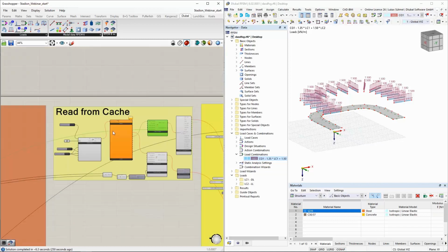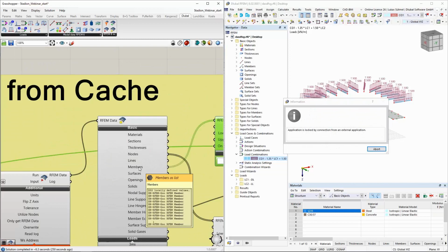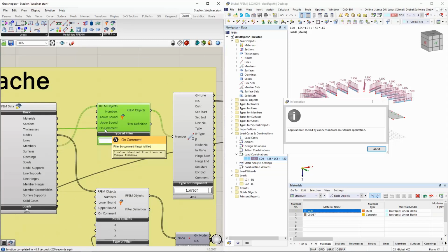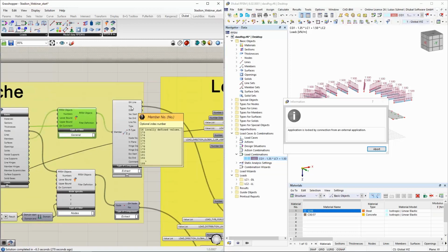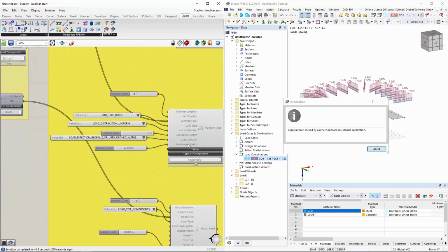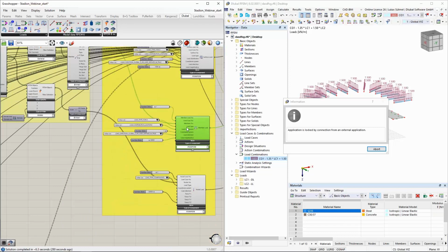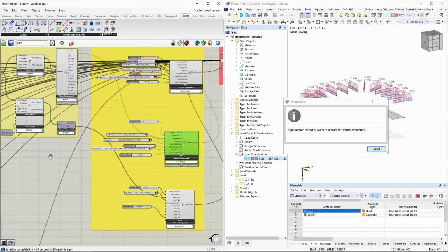So from these, and I can show it now, from these, let me see, 252 members that I theoretically would export, I filter according to Trägertribüne, to this comment, and I get here 16 members. And from those 16 members, I extract the ID, and this ID I assign to this member load component. That's the alternative way how you could, let's say, create loads. You either define the index number beforehand and then just connect the members to the loads, or you make this workaround via the theoretical export.